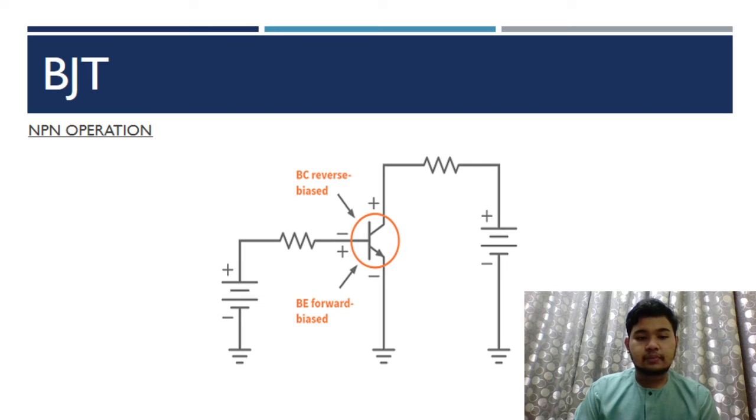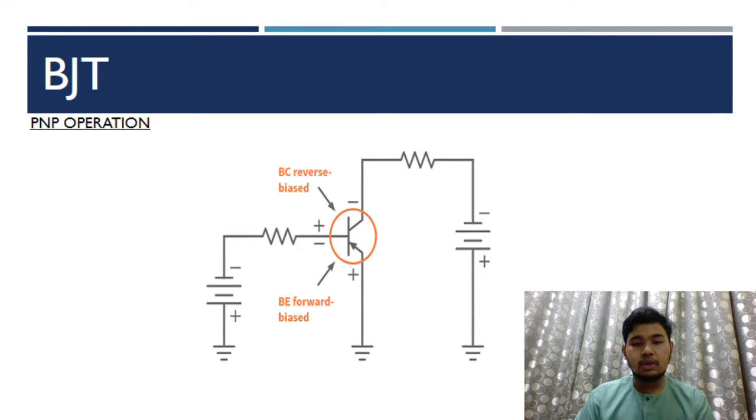The free electrons that enter the base region but did not recombine with holes move toward the reverse-biased base-collector junction. Since the collector region is connected to the positive side of the external bias voltage, the free electrons are attracted to the positive side and swept across into the collector region. They exit the collector region, move through the metallic collector lead into the circuit, and return to the emitter region.